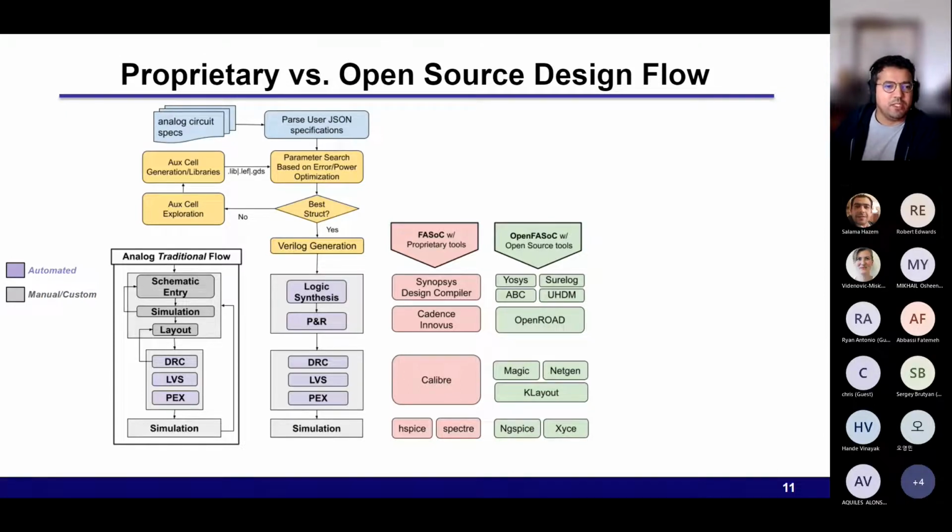And coming back to physical design, it is worth noting that using OpenROAD, we are able to use Tcl-based or, even better, Python-based APIs to easily do things that are a little more complex using proprietary tools, such as building macro functions to do symmetrical placement or arrays or guard banding. I'll get to this later in this presentation.